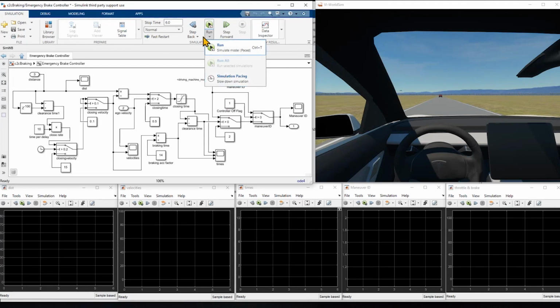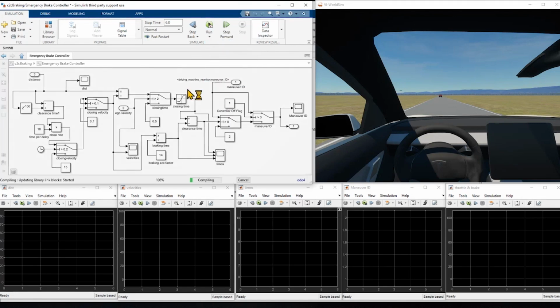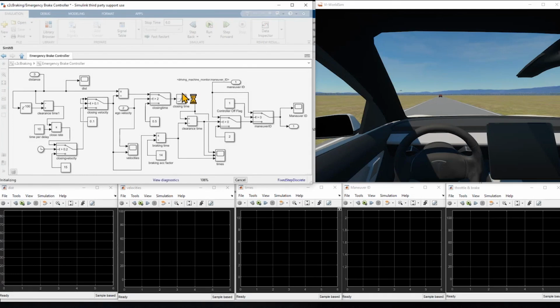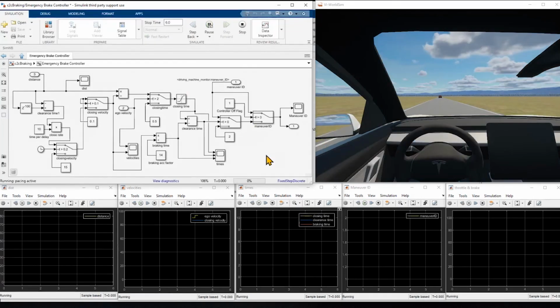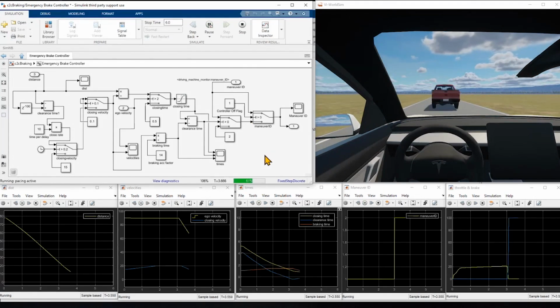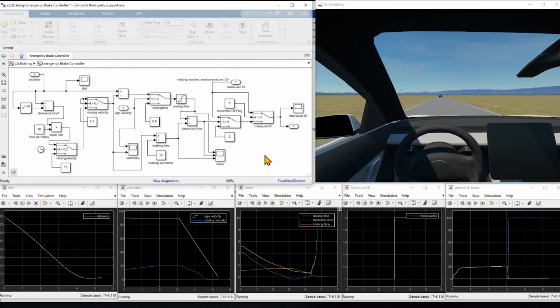And we're going to run it in a real-time way, because it runs faster than real time. So this controller is compiled. It's going to run. It's sending output out, and you can see in the upper right corner the WorldSim model running. And we went open loop, and at 3 seconds we hit the brakes, but it was too late. The vehicle crashed.